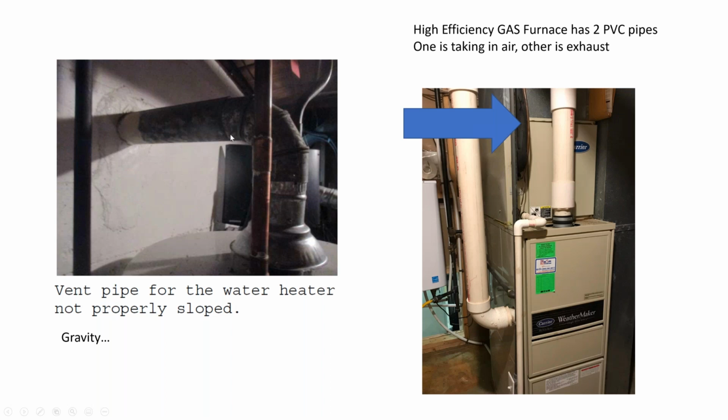I actually showed a house a few years back and the owner had died. It was in an estate. I walked over to look at the water heater, which looked ancient, and I looked behind it, and this vent pipe was completely rusted through. So it was just letting all of the carbon monoxide out in the basement. And I'm thinking, I hope that wasn't what killed this poor person, because it obviously had been like that for years. It was just gone, disintegrated because it rusted out. So now they use PVC, so it doesn't rust out.